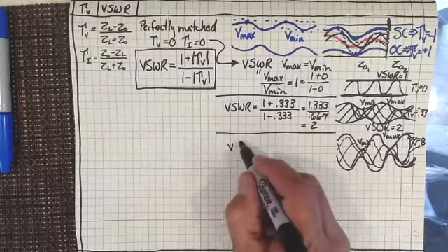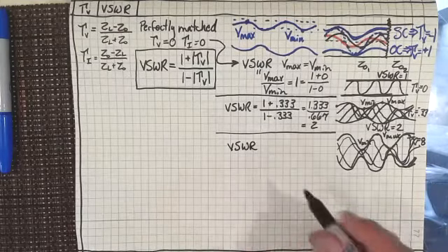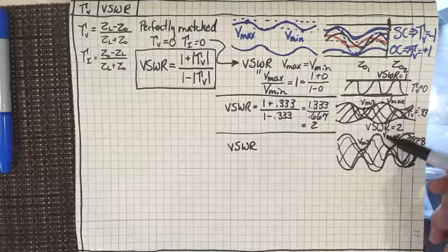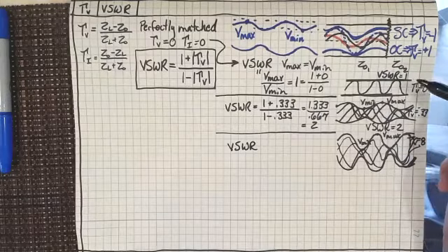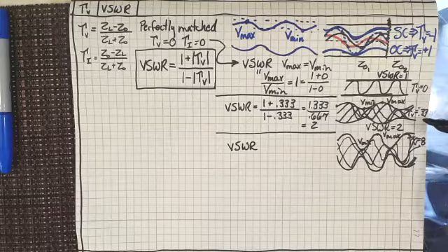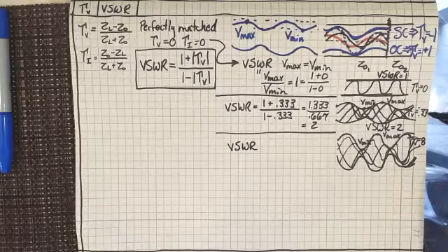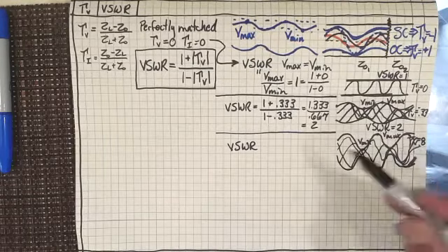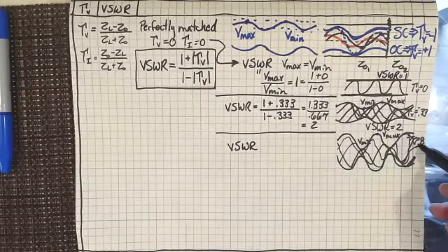Now, what's my voltage standing wave ratio? And you can see that V min over V max now is much larger than it is here. So we're starting at a reflection coefficient of 0 with a VSWR of 1. Then we're looking at a reflection coefficient of about 0.33 or minus 0.33. I could have made this a minus, but I think I've already made my point.